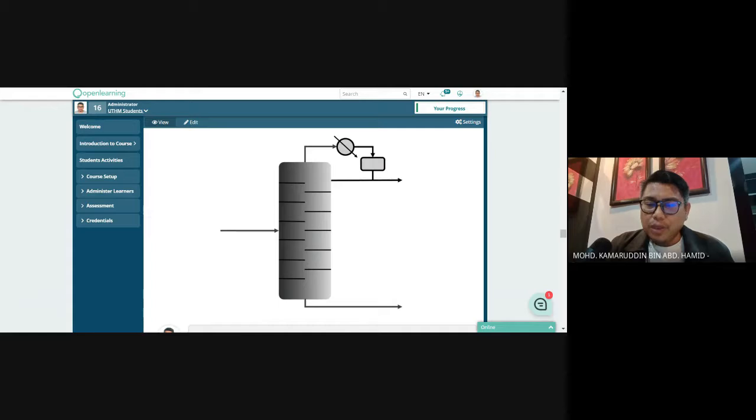If you use a partial condenser, then you may have liquid and vapor as products. If you have a total condenser, then you totally make all the vapor become liquid. That's why we call it a full or total condenser. Okay, so in this one we have the owner's body, which is the absorber, plus a condenser. So what do you call it?